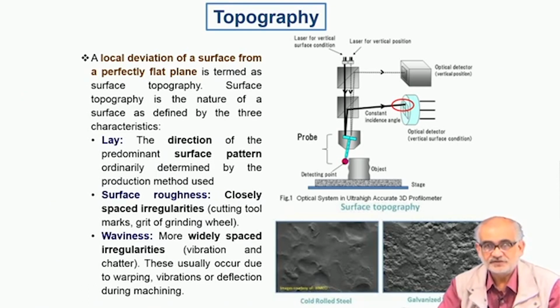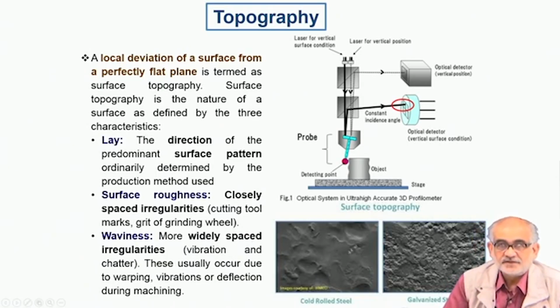For example, you can see here that this is a cold rolled steel sheet, and when the sheet comes out of the roll, it appears very shining, and normally you would not expect that the surface can have such dents or certain surface deformation marks. And these dents could be just hardly a micron, even less than a micron in depth.